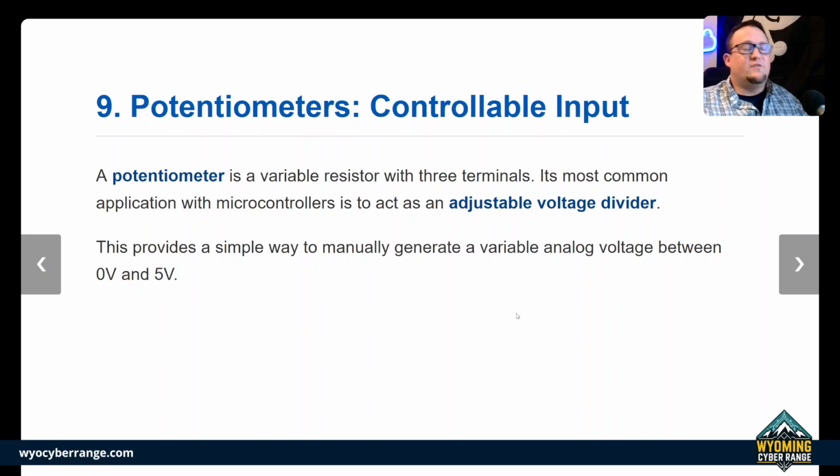Depending on how much you turn the knob to the right, it turns up the voltage on the signal to the speakers. The higher the voltage, the louder the sound. The lower the voltage, the lower the sound. So a potentiometer is just a variable resistor. Instead of putting a resistor in front of my LED, maybe I put a potentiometer instead. This way I can control it.